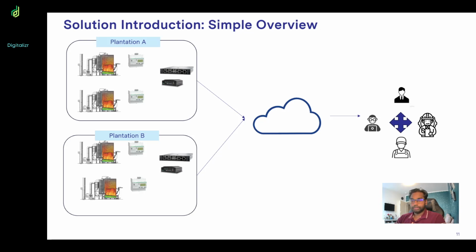So for this situation, we will normally use IoT edge devices or something like industrial computers, most familiarly known. We connect those Schneider PLCs through an Ethernet cable. You just need an Ethernet cable to connect to the industrial PLC.